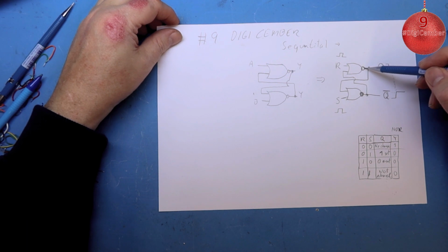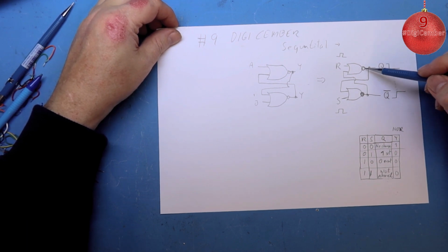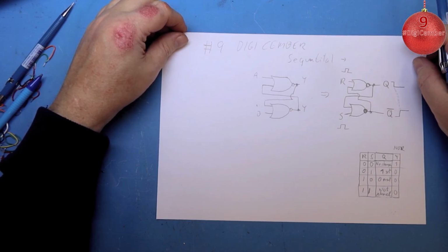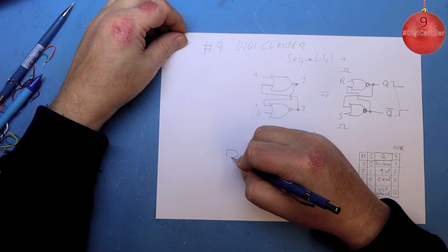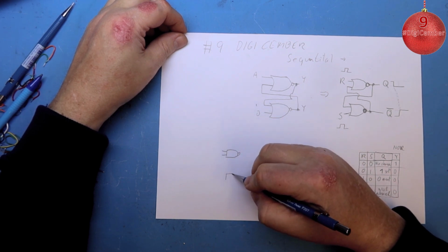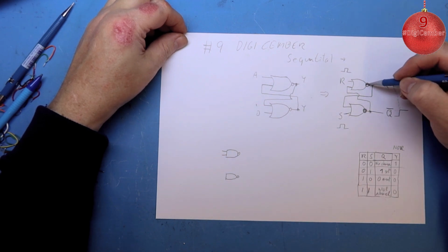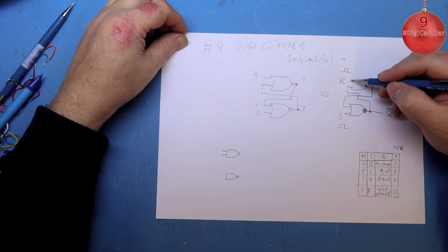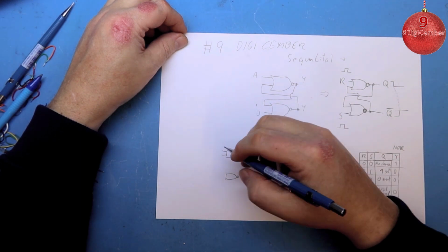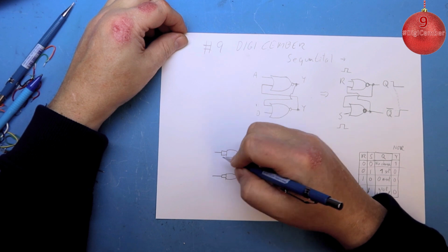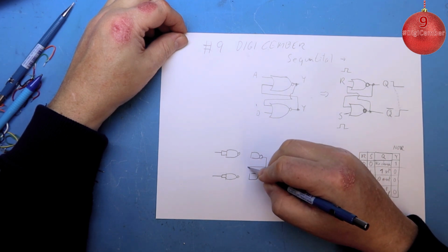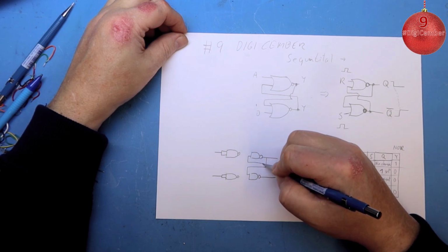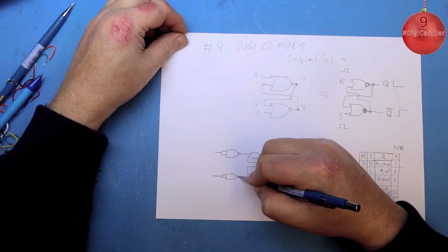And we are going to make these circuits on the breadboard, but we are going to do so with NAND gates, like we did before with the 7400, where we used this to make our XOR gate. We are going to use the same chip. And how we do that, I'm going to quickly draw a principle of this here. A NOR gate is essentially a NAND gate that also has inverters on these signals here. So if I'm going to do the simplest inverter, I'm just going to couple these two together, and then I'm taking the next gates and I just do this trick here, and like so, and like so.